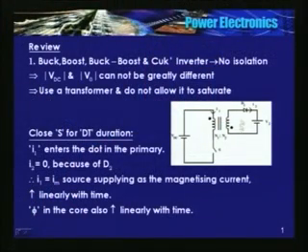The principle is that we should not allow the transformer to saturate. So, we discuss the operation of this circuit. We use a transformer between the input and the output. We used at the output also a separate voltage source, and we connected a diode in the secondary in such a way that only one winding is carrying current at a time. Okay. So, when we close the switch, current enters the dot.